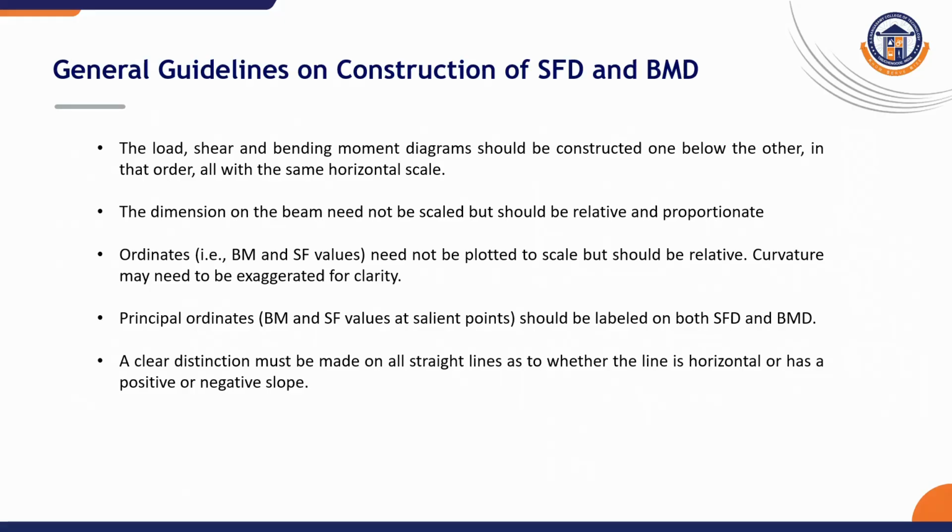General guidelines for construction of shear force diagram and bending moment diagram. Some important guidelines are: the load diagram, shear force diagram and bending moment diagram should be drawn one below the other. Use the same horizontal scales. Ordinates need not be exact but should be proportional. Label important values clearly and show the sign conventions properly. Neat diagrams improve clarity and the understanding of the shear force and bending moment diagrams.